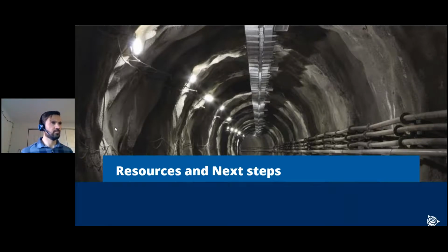Just came in. Oftentimes we lose GNSS connection inside a tunnel. Do inspection scans need to be shot from the exact same location for accurate results? Hey, Dane, thanks for the question. So this is where I think the real power of the SX12 is because when you scan with the SX12, it will reference to your survey control.